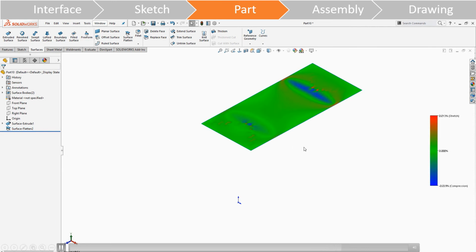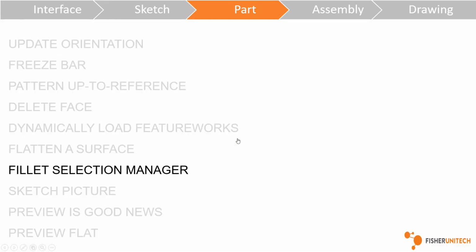And then from there, if you right-click on it, you can actually get a deformation plot, right? So it's going to show me how much this thing was pushing or pulling, what type of tension or compression is going on, and give you that scale, right? So I could shoot that off to wherever I need from there.